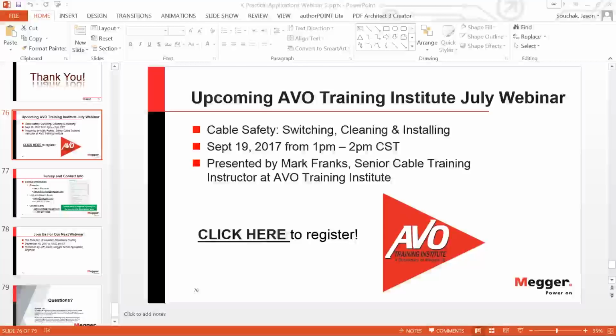Yeah, okay. I agree with Henning on that. Exactly, tan delta testing on new cables is not going to hurt anything necessarily, but what kind of information do you get from it? Wait till you come out and do your first scheduled maintenance on it, a year or even 5 years out, and that can be your baseline then. 5 years of aging on a cable is not going to be too much.